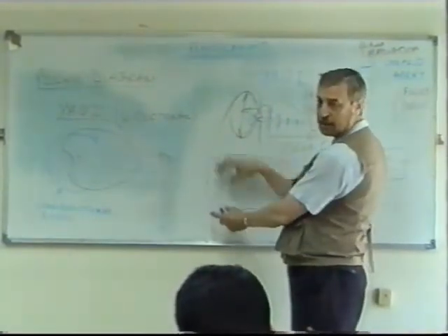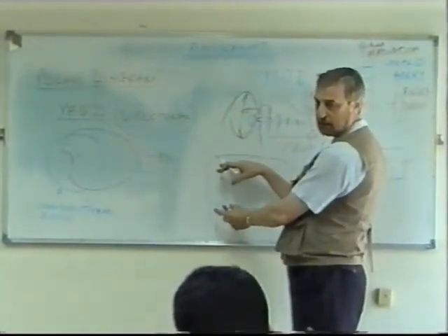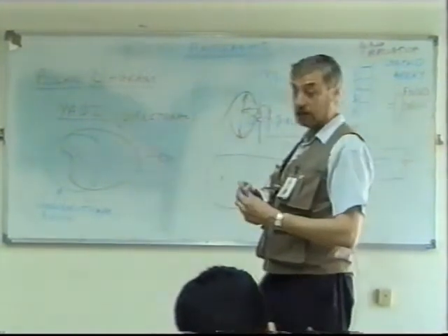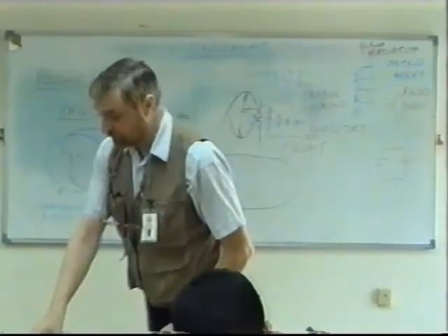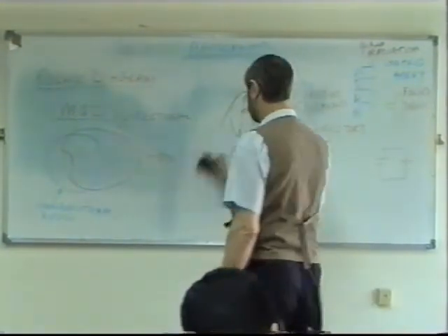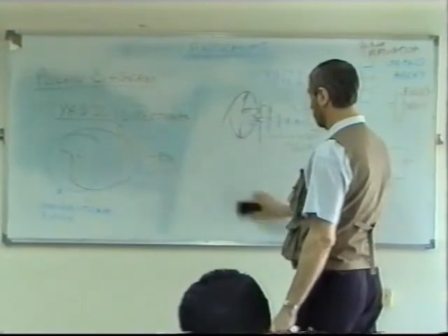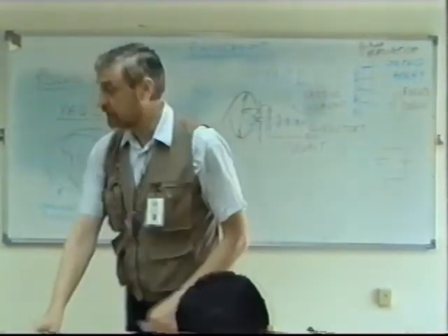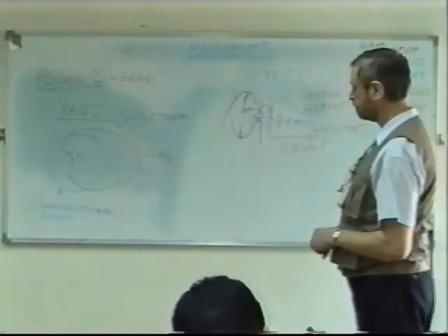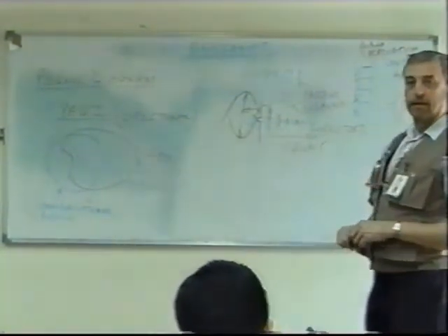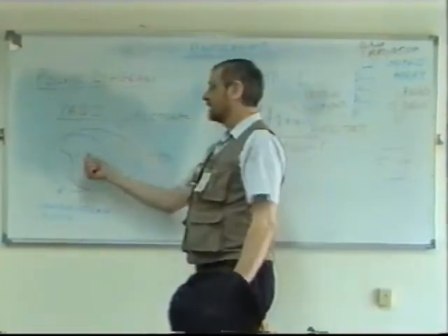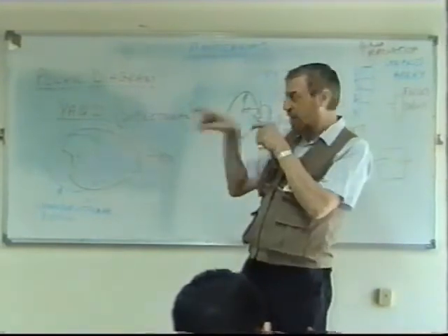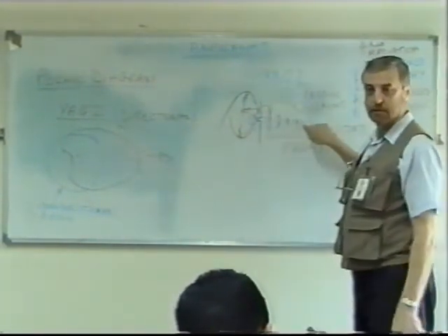In other words, you have up and down directionality as well, but again, most of it forward. I've never really considered a Yagi side view diagram, but something like that probably. Anyway, we can see here that it certainly is directional in one direction. And the direction is where the elements narrow out.